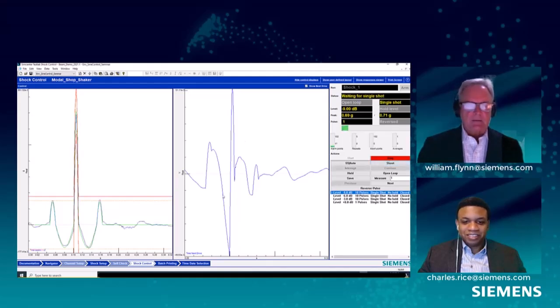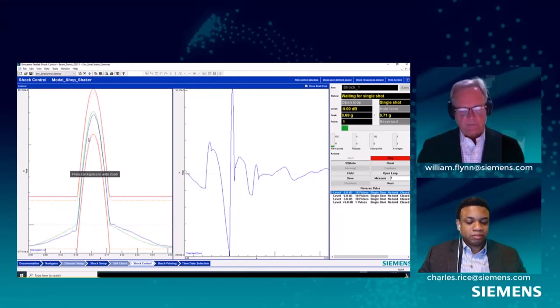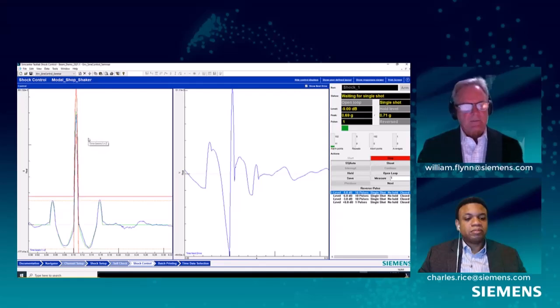And you can see the drive out here is the predicted drive. There are some phase relationships between acceleration, displacement, and all. And also, of course, based on the transfer function of G's per volt with this system, that allows me to calculate the voltage out of my DAC, and that's shown in this display here. It's showing some pretty good response just from the initial estimation from the self-check of my transfer function.